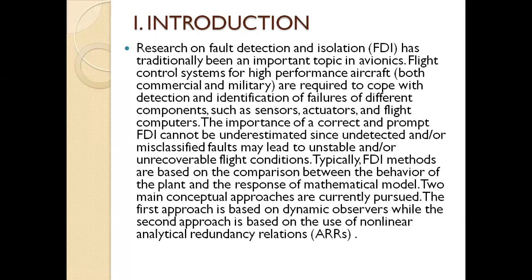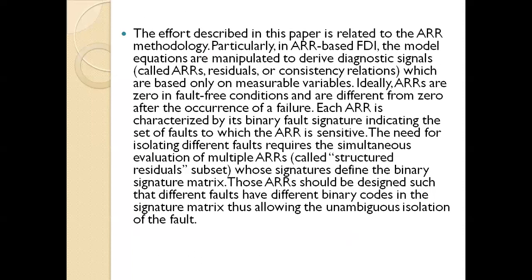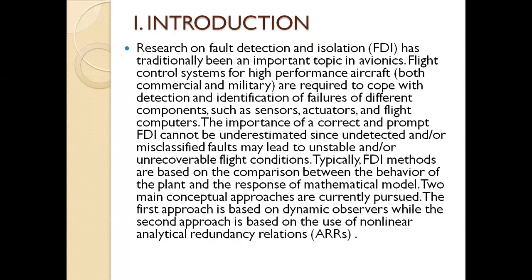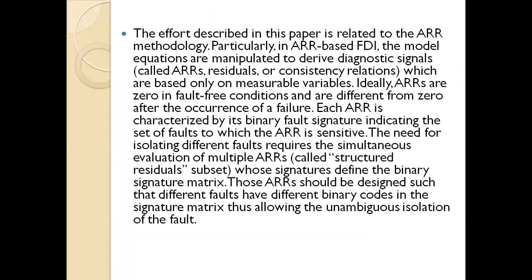Typically, FDI methods are based on the comparison between the behavior of the plant and the response of a mathematical model. Two main conceptual approaches are currently pursued. The first approach is based on dynamic observers, while the second approach is based on the use of non-linear analytical redundancy relations (ARRs). The effort described in the paper is related to the ARR methodology and analytical redundancy relations.